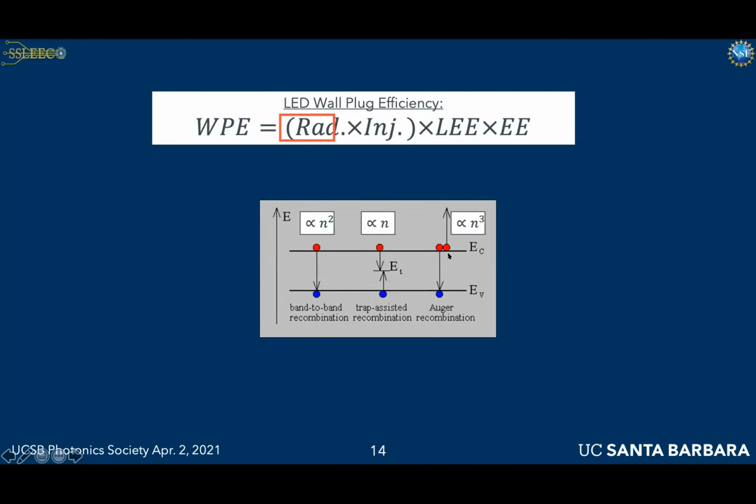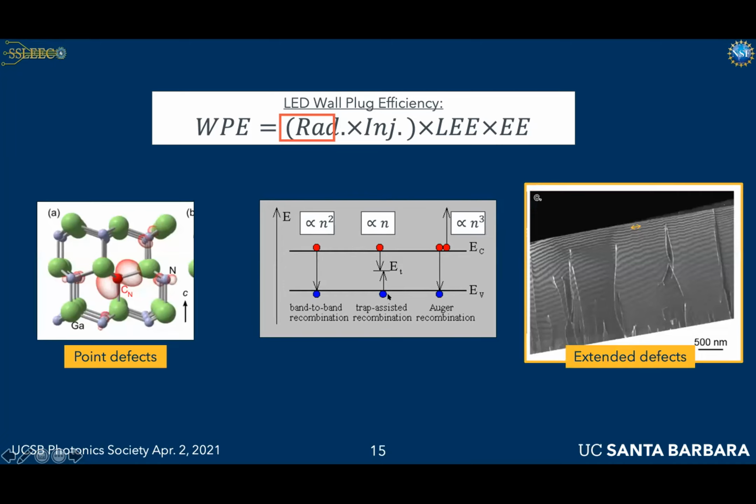And you also don't want them to give the energy from the recombination event to another charge carrier, such as an electron in this picture. That's called Auger recombination. For now, we're going to focus on this one in the middle here, what they're calling trap-assisted recombination or Shockley-Read-Hall recombination, which occurs wherever you have defects. And you don't want that. So what it comes down to, pretty simple, is you just want to reduce the number of defects in your material.